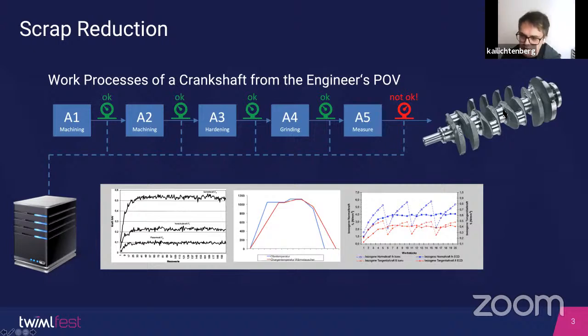And also these surfaces are not on a common axis on this part. So usually you have those surfaces on a common axis. It's not the case here. And from a production point of view, that's a nightmare. If you have that, it's very, very complicated to do it well.